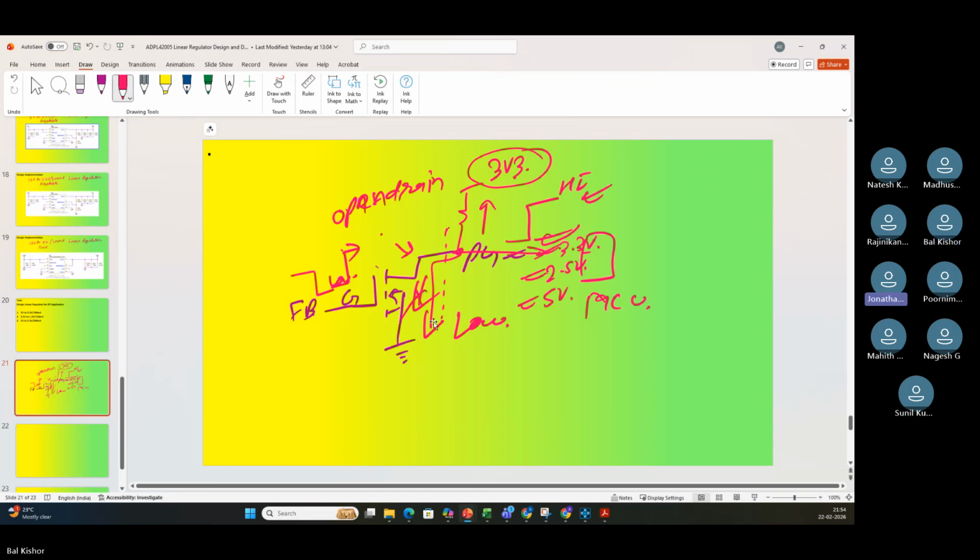So does that mean in PG, if it falls below 90%, that means the PG will be high? Correct? Yeah, because FB pin is not indicating that you short circuit the MOSFET. Like it is not turning on the MOSFET. Okay, yeah. So basically, if it goes below 90%, your P good will be high. So that means your LED will turn on, in that case, if you have an LED.